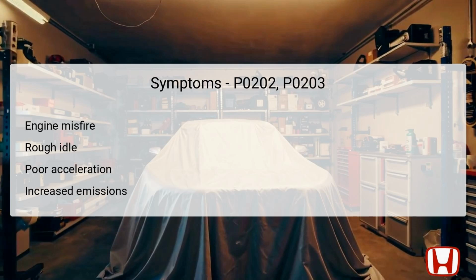Additionally, drivers may notice poor acceleration as the vehicle struggles to receive sufficient fuel to maintain power. Lastly, increased emissions can occur as incomplete combustion processes lead to unburned fuel passing through the exhaust system. Recognizing these symptoms is crucial for prompt troubleshooting and resolution.